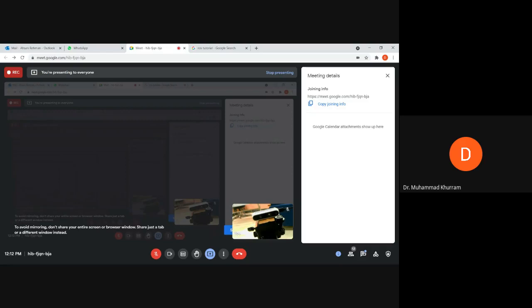Okay, so the camera does not have very robust nighttime capabilities, but it is powered by IR cameras. As you might know, the IP cameras or surveillance cameras which have night vision capabilities are powered by IR sensors. So we have an onboard IR sensor on the Intel RealSense D435i, which is the model of this sensor, and it can operate under certain limited capabilities at night time. Since it is a very raw sensor, we can access it.